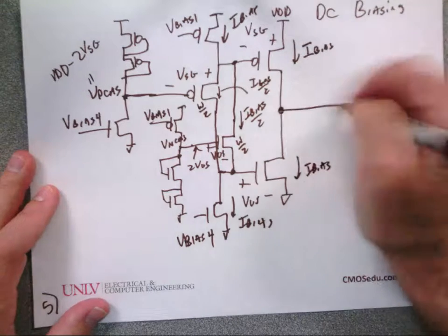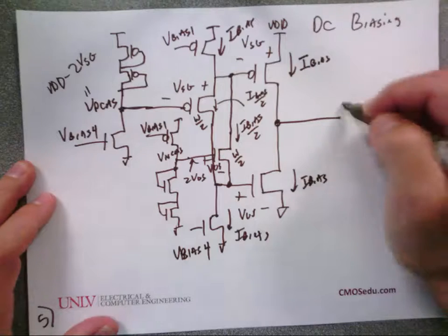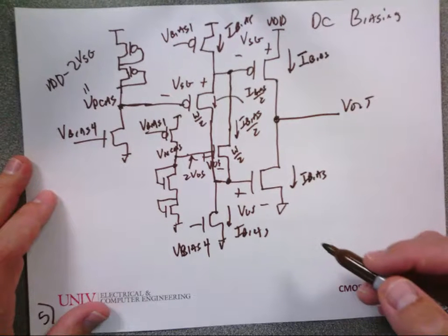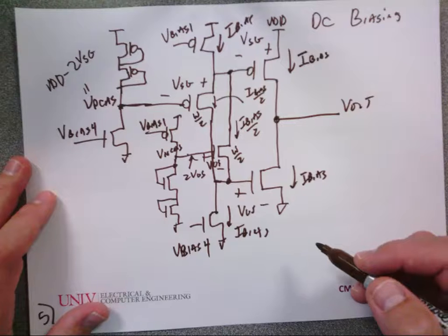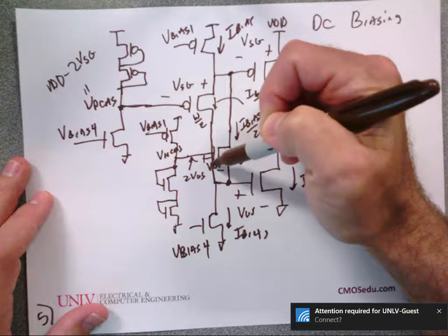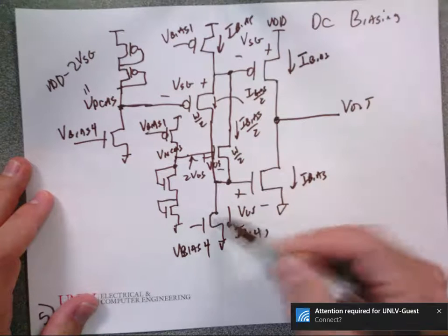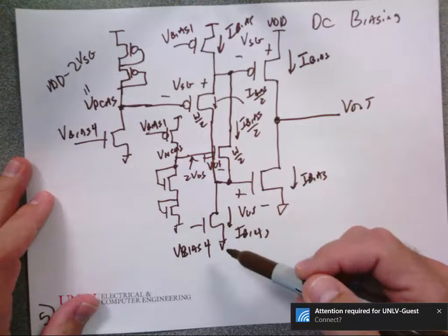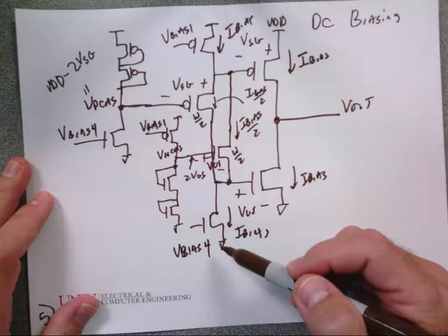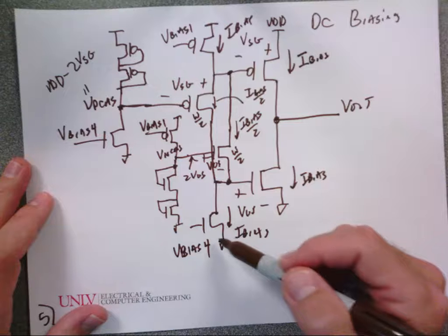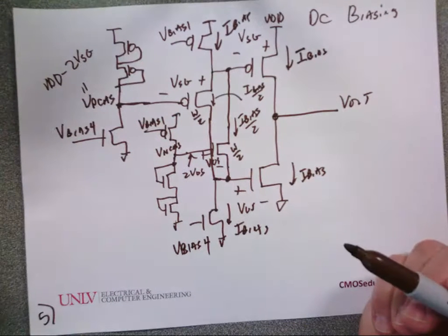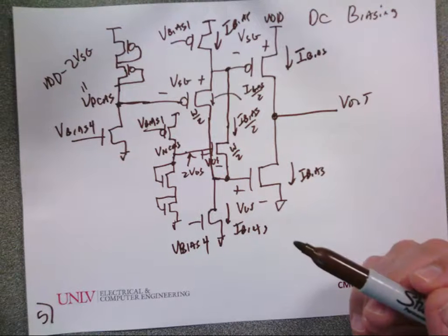What do I label this node? Just, yeah, V out. The output of the op amp. Can you explain the I bias and I bias over 2? So these, just a normal transistor. These two are half the sizes. So half the current flows in them, and this is a normal size transistor, so I bias flows in that. How do you know that half the sizes have half the current flowing through it? If I change the width by a factor of 2, the current drops by 2.